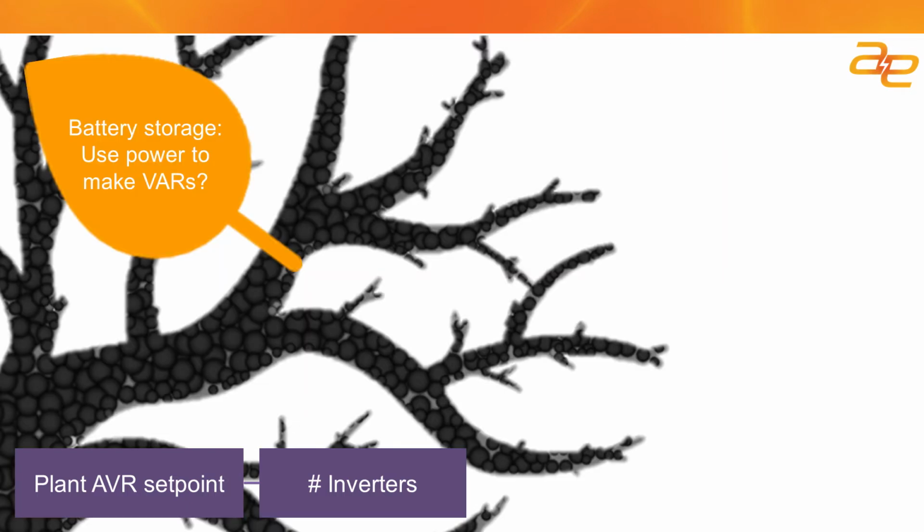Again, we have battery storage. We can use battery storage to deliver kilowatts, or we can use battery storage to deliver VARs. I've seen a lot of business cases put together that if a solar site is big enough and there is enough need on the transmission line to supply ancillary services, you may have battery storage on a site purely to do VAR support on the grid if there's a voltage deviation. And there's certainly a business case for that.